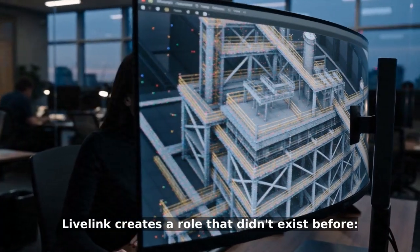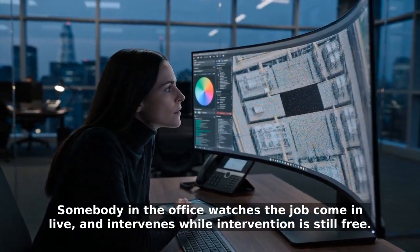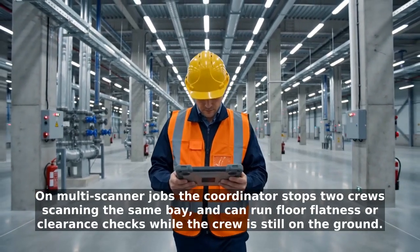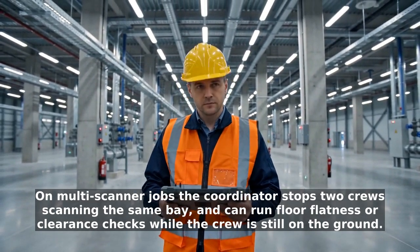LiveLink creates a role that didn't exist before: the scanning coordinator. Somebody in the office watches the job come in live and intervenes, while intervention is still free. On multi-scanner jobs, the coordinator stops two crews scanning the same bay and can run floor flatness or clearance checks while the crew is still on the ground.